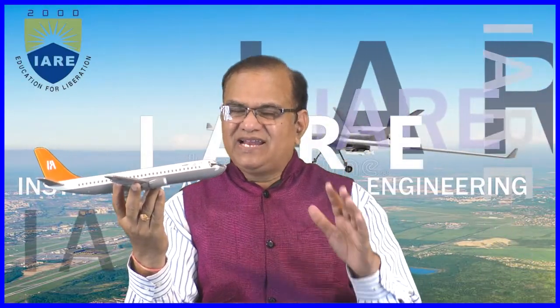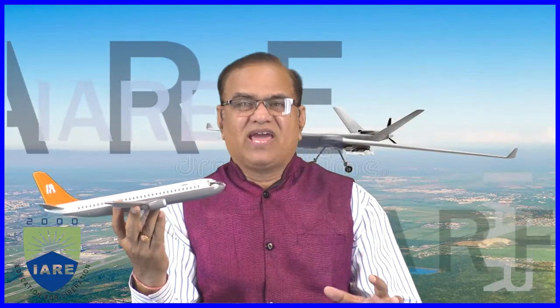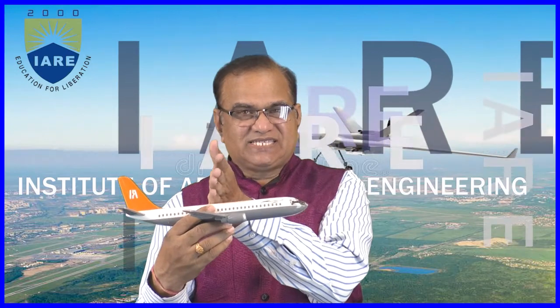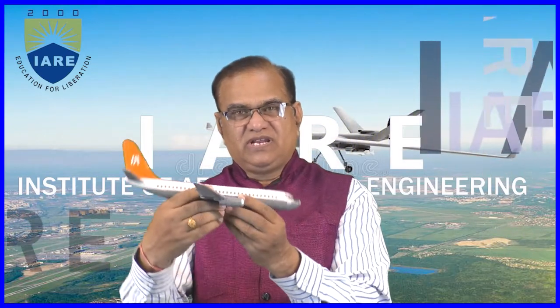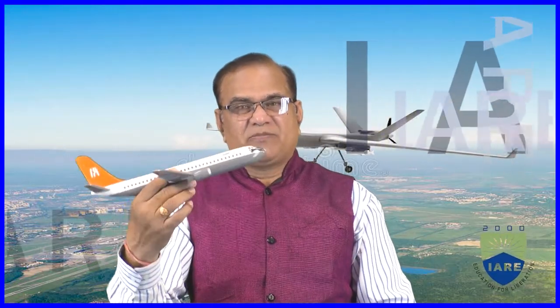So it is an ideal condition which we can simulate in a wind tunnel. In real flying, pure pitching is not possible. However, if we fix the aircraft inside the wind tunnel with a bearing on the y-axis, the aircraft can move about the y-axis, so longitudinal motion will take place. Only pitching up or pitching down.